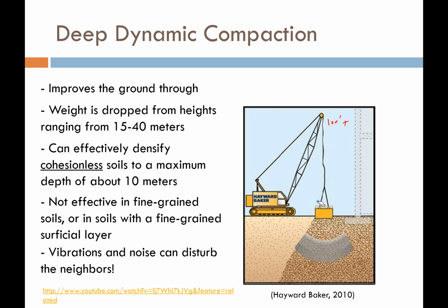When you bang a weight that heavy into the ground, it's going to send waves down into the ground, and those waves are going to compact the soil down to depths of up to about 10 meters maximum. But they're only effective in compacting cohesionless, not cohesive, soils. So this really is going to work by densifying the soil. That's the only thing that we're doing. We're not adding any new soil to it. We're just densifying it from the ground up.